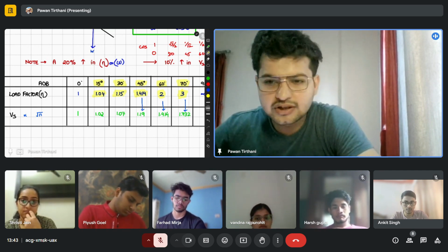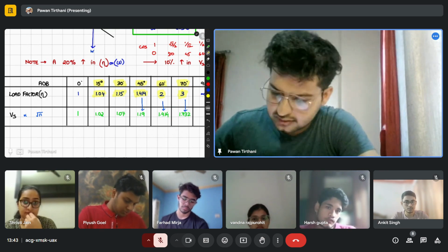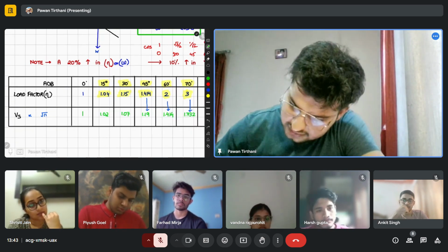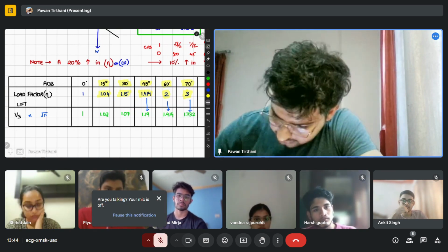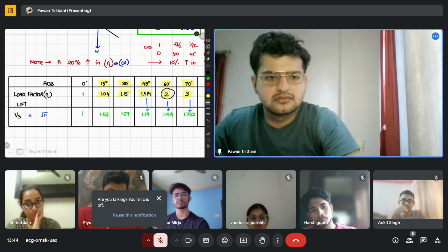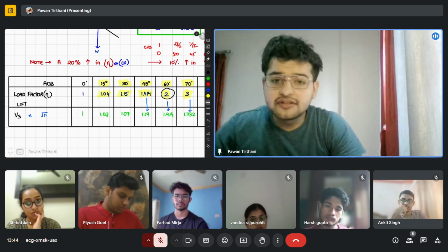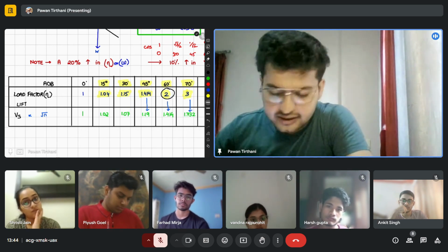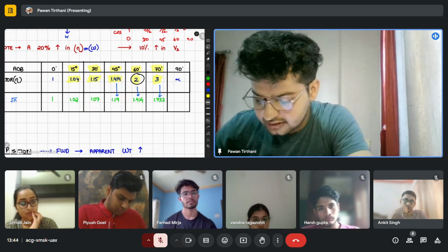सो अगर कोई तुमसे पूछे कि लिफ्ट कितनी बढ़ी, लोड फैक्टर कितना बढ़ा, है ना? इफ इन द एग्जाम यू आर आस्क्ड कि इन अ 60-degree बैंक लिफ्ट इंक्रीजेस बाय हाउ मच, लोड फैक्टर इंक्रीजेस बाय हाउ मच, आप ये वाली वैल्यू दोगे. बिकम्स 1.414 टाइम्स. अगर आपसे पूछे इंक्रीजेस बाय 41%, तब परसेंट बोलोगे. ठीक है, लेकिन अगर स्टॉल स्पीड पूछेगा तो इसका रूट कर देंगे. रूट, रूट. अब रूट करने की मस्त तकनीक सिखाई थी मैंने अभी आपको.